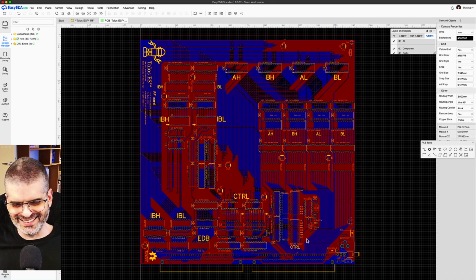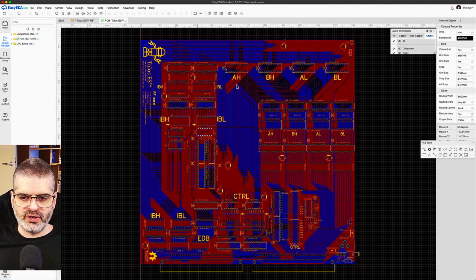We're almost there. And now the control signals come from the backplane connector in this area here, or they can be set by these 2 switches with their respective little resistor networks to pull the signals down so the switches work. And these 4 buffers here will then select whether the control signal values come from the backplane or from the switches. Either way, the result is inverted by these 2 inverter chips, and then they are spread around the board to control everything.